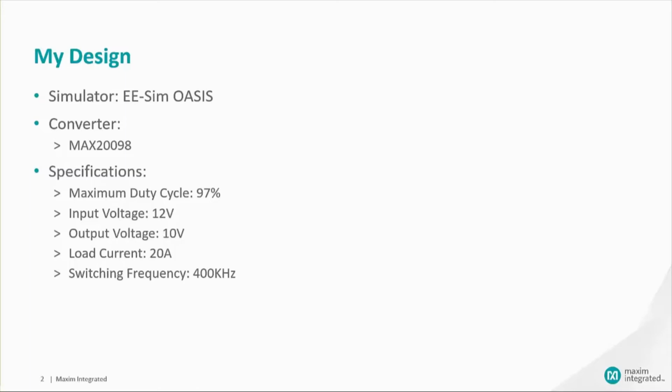For my design, I am going to use MAX20098. The MAX20098 has a maximum duty cycle of 97%. My design will have an input voltage of 12 volts, an output voltage of 10 volts, a load current of 20 amps, and a switching frequency of 400 kHz.